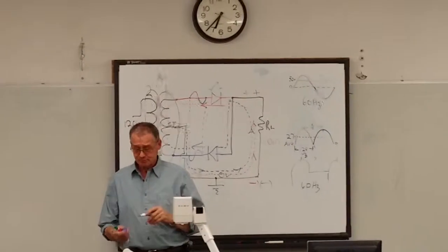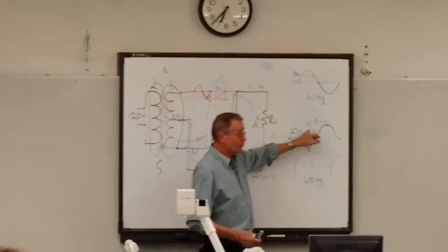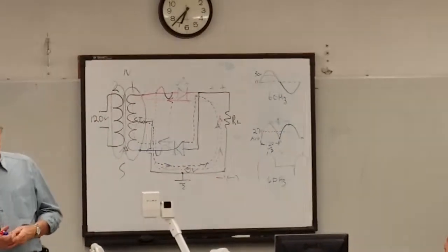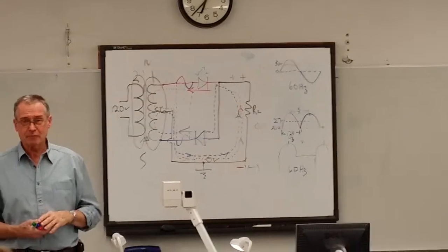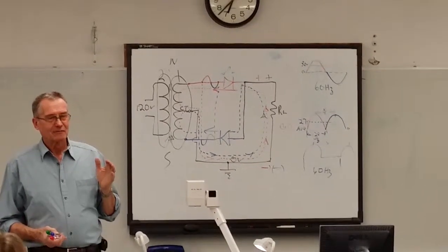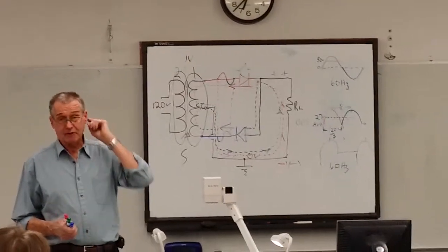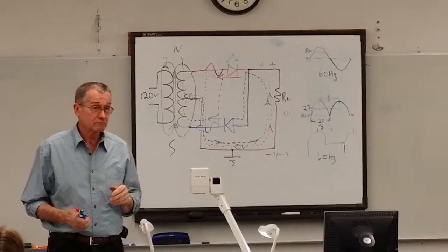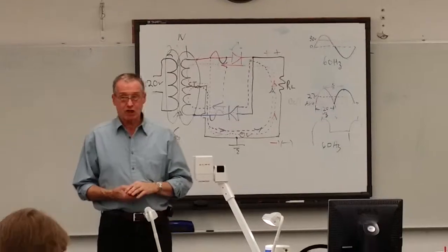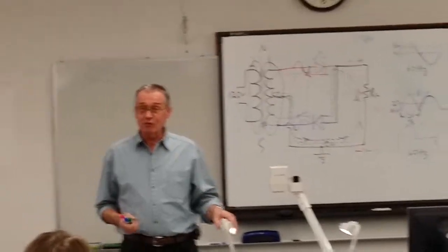So what that means is, if this requires a 1,000 microfarad capacitor to filter it, this would only require a 500 and get the same amount of filtering. Why is that important? Because other than the transformer, the capacitor is the most expensive part you can have in a power supply. Capacitors are typically in the 1,000 to 5,000 microfarad, up to even 10,000. A 10,000 microfarad will cost you about $8, where a 5,000 would cost about half that, about $4.